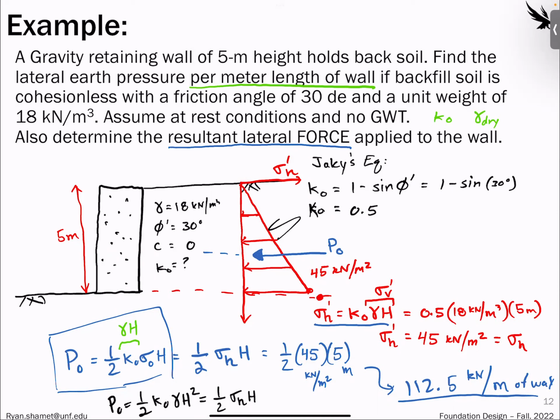And so that would mean if your K value is different, then your stresses are different, which means your horizontal stresses. But the important thing that Coulomb and Rankine did, they also looked at if it's passive or active, then that means the soil is going to be moving, right? Either the wall is moving out or the wall is moving in. The soil is going to be moving. So the angle at which the soil is moving is important. And that's where we'll catch up in the next class.